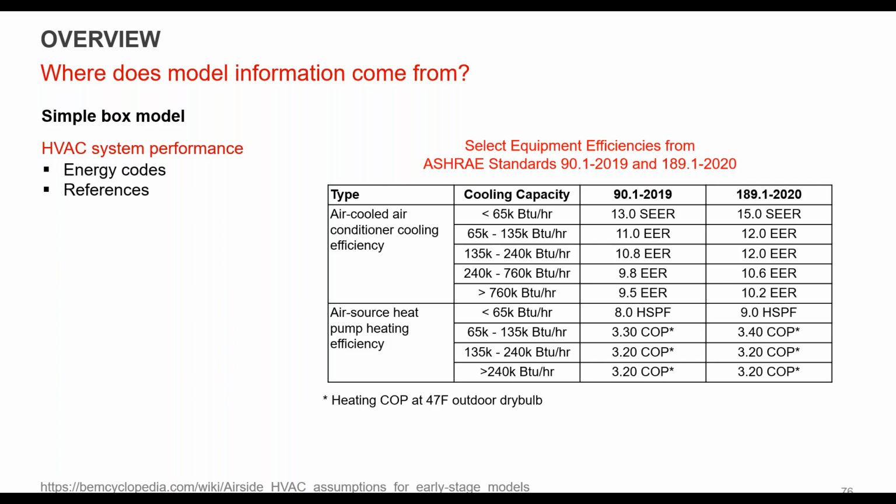Luis asked, are the internal heat gains per person uniformly distributed in a simple model? Yeah, they can be. I guess it depends on how many zones you have. You might know that you have one zone. A lot of times, like the one we're doing now, that's a theater, it's got a theater and 2 support spaces. So that theater zone, we have a very specific 350 people in that theater. And the other one is an office, and the other one is like a lobby corridor space. So you might have 3 use types. If you don't even have that much, if it's like an open office and you don't really know, you might be uniformly distributing your loads across the different spaces. It kind of depends. Good question though.